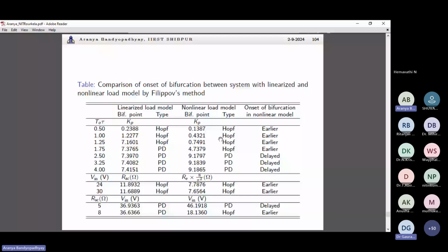But when it comes to the period doubling bifurcation, note that you can't predict this type of instability with your Bode plot or state space average based approach. Then what we are seeing is a type of delayed instability. That's why I had told you to always get rid of any preconceived notion when it comes to science, because surprising things might often turn up.